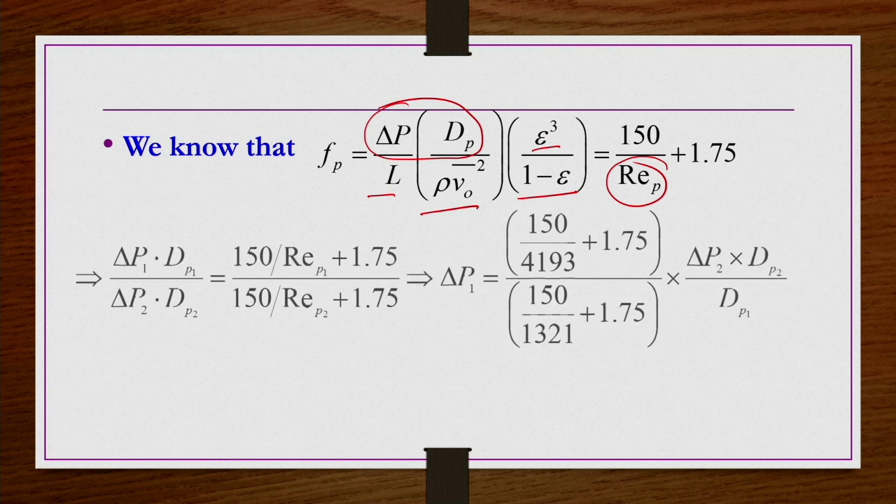So that reduces our calculations. When we do this, delta P1, let us take the present case, because Rep1 I have used 4193 in the calculations. So delta P1 would be the present case here. Only delta P1 is not known. dP we just found as 0.44 mm or so.